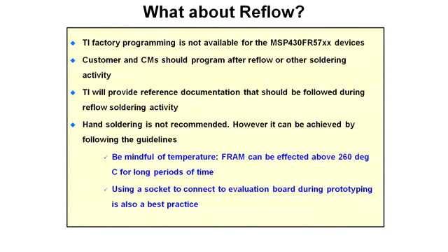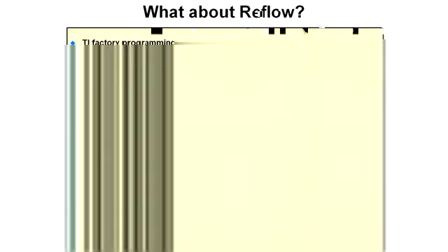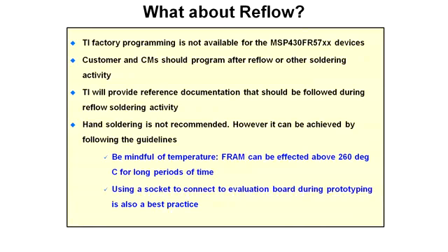FRAM devices are somewhat susceptible to higher temperatures. TI factory programming is not available for FRAM devices. You should program the devices after reflow. Follow the documentation when you're doing reflow soldering activity to the board.